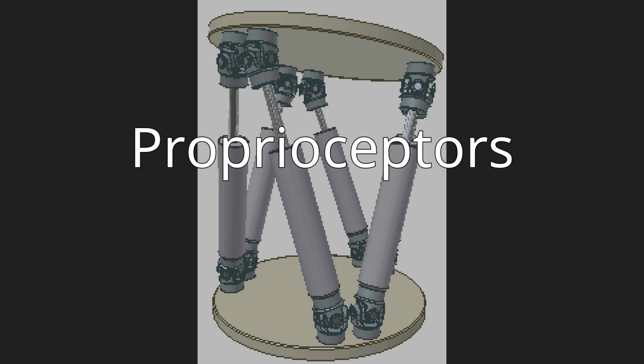In simulator motion platforms, after an initial acceleration is produced, the platform is reset to a neutral position at a rate below human motion threshold so that the subject does not detect the so-called washout phase of simulator motion cueing. The motion system is then ready to make the next acceleration, which will be detected by the subject, as in the real world. This so-called acceleration onset cueing is an important aspect in simulators with motion platforms and models the way humans feel motions in the real world.